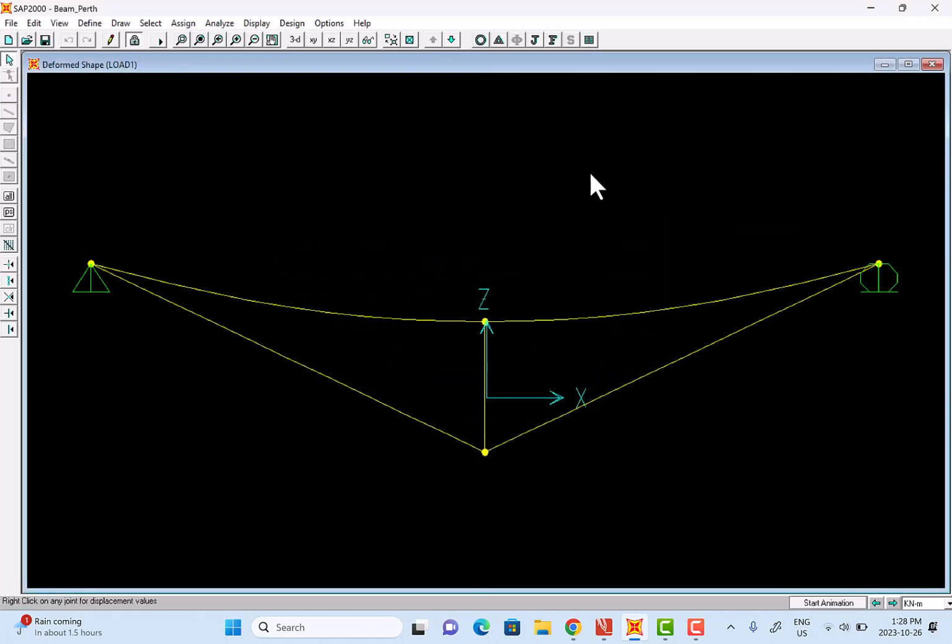And what I've got is the deflected shape. You'll notice that the truss members have stayed straight, and they should. The way we define it with just the pin-ended members, these should just be subjected to axial forces, either tension or compression. But you'll notice your beam has a nice curved shape there, and that's good because we have those loadings. Well, it's consistent with what we're trying to model here. Because we have loadings applied along the length of that member, that's not going to stay straight. It's actually going to undergo bending.